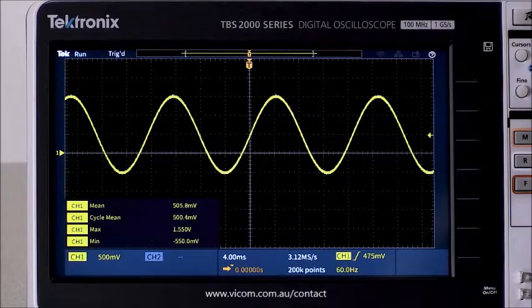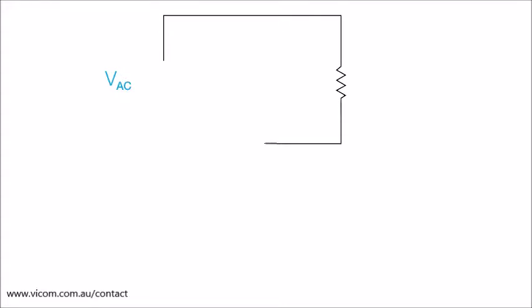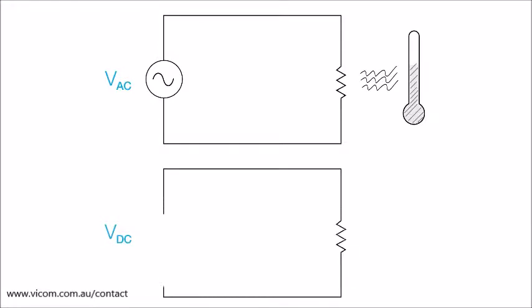But if we want to understand the energy in a symmetrical waveform centered around 0 volts, like this, the fact that the mean is 0 volts doesn't tell us anything about the amount of energy. Root mean square, or RMS, is another statistical measure of a signal. You can think of RMS as a kind of mathematical AC to DC converter. For an AC waveform, RMS gives an equivalent DC value that would generate the same heat or deliver the same amount of power.